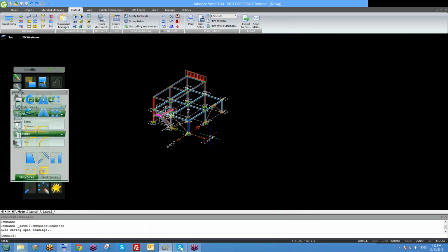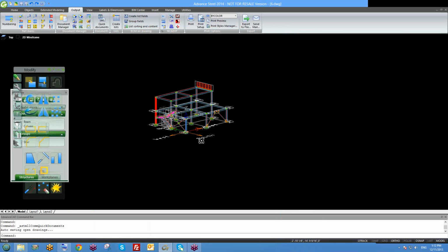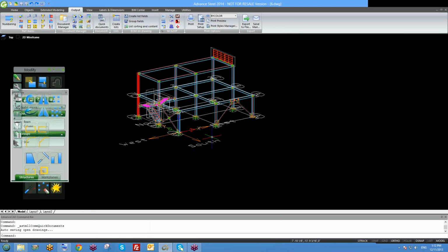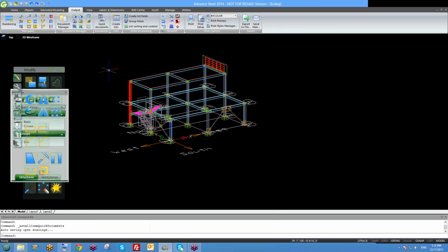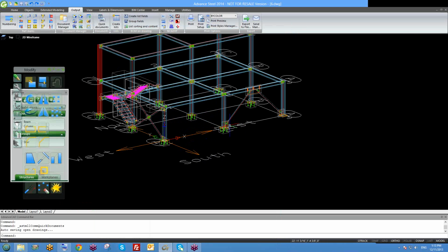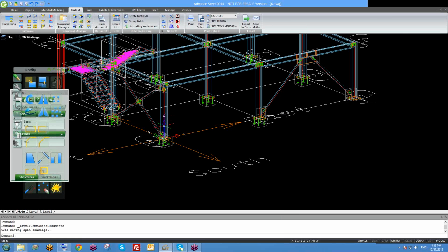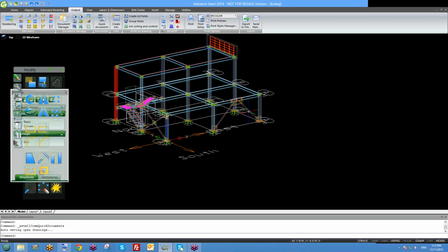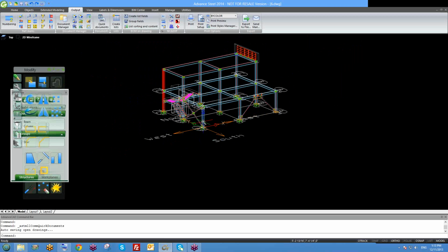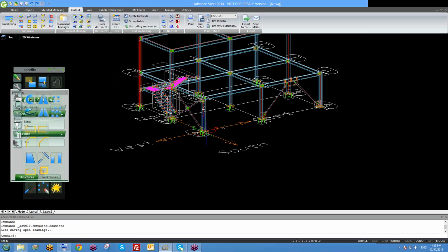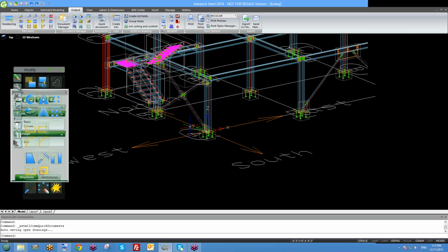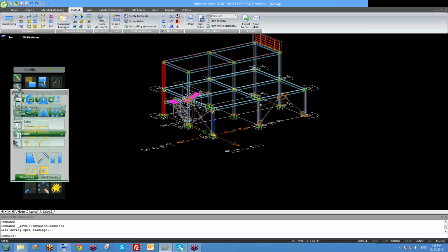All right, so now let's start making some drawings. I'm going to start with my anchor plan. To make my anchor plan, first of all, I need to have my Z like this. So X and Y, Z is up, no matter where in the model. Get your X and Y aligned with the plane you want to make your drawings for.